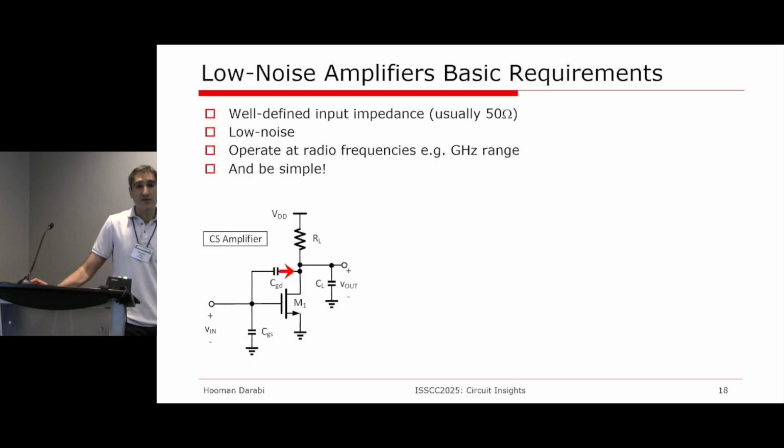It also, at high frequency, makes the amplifier non-unilateral. You'd like your amplifier to be unilateral. CGD will break that. The output capacitance CL, along with the load that you want to maximize to achieve the best gain that you can, will also give you a low-pass roll-off. You saw that in the examples of wireline building blocks. So those must be avoided, or somehow, without causing too much complexity, has to be fixed.